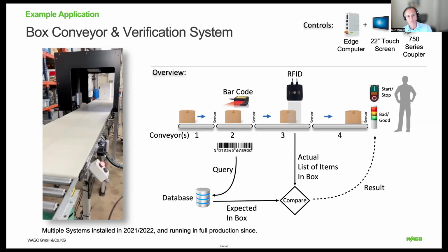There were some issues also with the barcode scanner. They were, sorry, they were TCP, native TCP socket connection type interface, and we did get that to work, but it really took like several hours to get it to work. With Node-RED, it was really as simple as dropping the TCP node, putting in the IP address, and you're instantly getting the data out of it. So it's really night and day how quick that development happens in Node-RED versus the runtime.